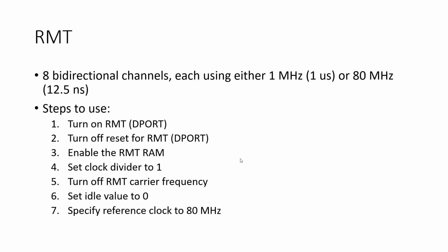Those are all the signals coming from all the hardware peripherals, basically. One of those signals is GPIO. So like, in Arduino, when you just say digital write, that's where you just put a constant on the I/O. That's only one of the 200 possible signals that can be connected to those, right? The RMT and the LEDC are other possibilities, right?